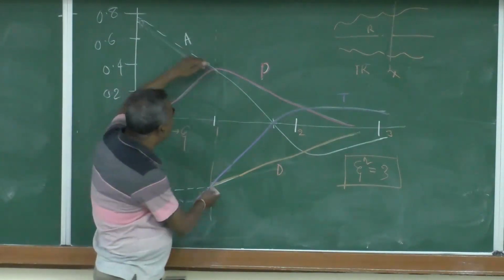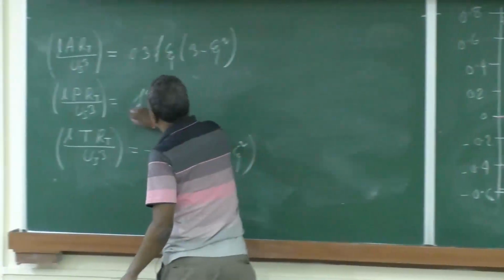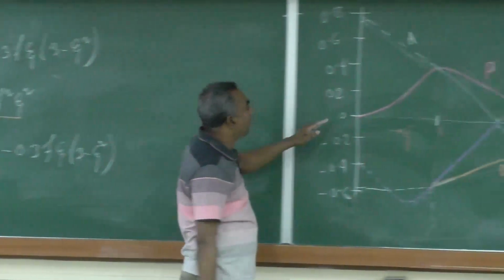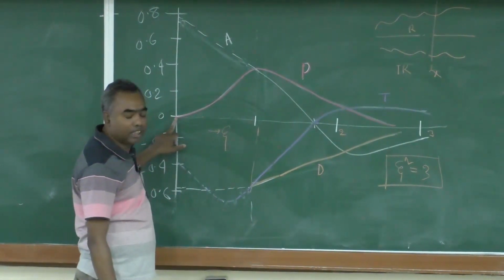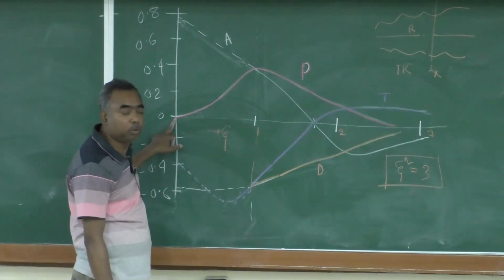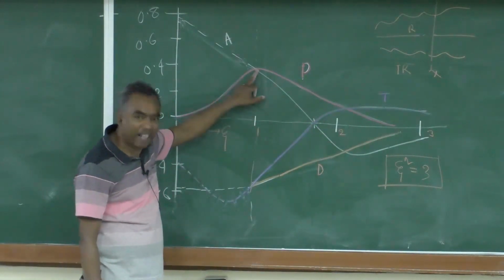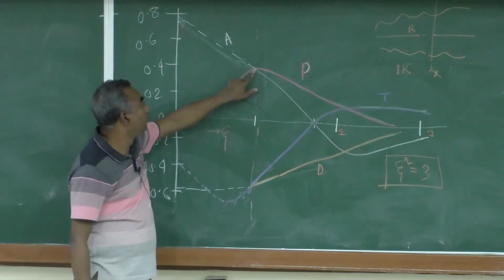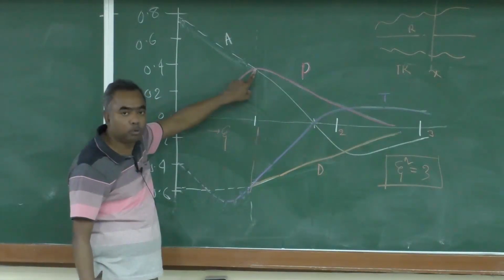Okay. And production, if you see production from this equation, at j equal to 0 it should be 0, because shear is 0 at that location. So, production should be 0. Production can be said to vary like this, and production is going to be maximum where the shear is maximum. The shear is going to be maximum where j is equal to 1, that is what we have found from the velocity profile, keep it in mind. So, the production term is going to be maximum here.